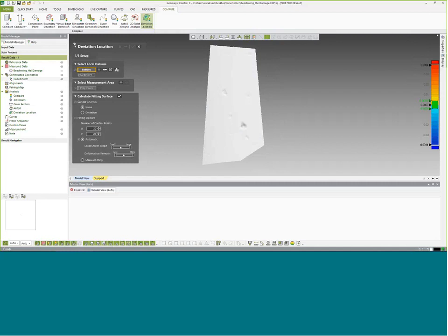But I'm just going to use a little automatic function today. So there's a couple things we can control in here. We can control how many points make up that patchwork of essentially that NURBS surface that it's going to make. The more points that we have, the more accurately we can fit the surface. But for smooth sections, stuff that's smoother, using fewer points is always nicer. Just creates a nice smoother surface.